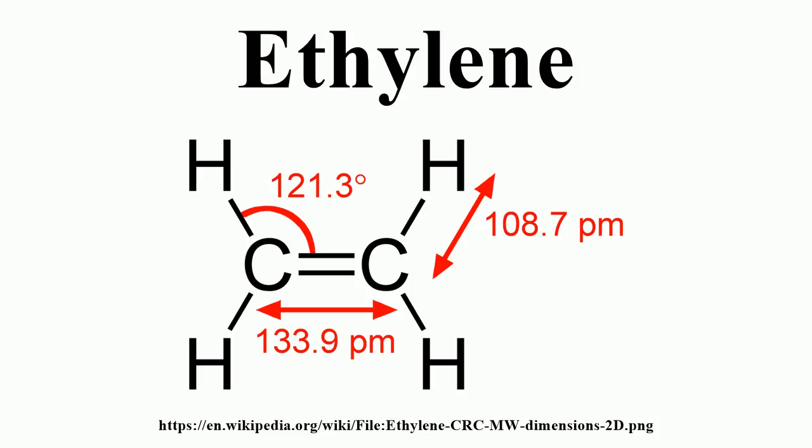The bottom stream from the deethanizer tower goes to the depropanizer tower. The overhead stream from the depropanizer tower consists of all the C3s that were in the cracked gas stream. Before feeding the C3s to the C3 splitter, the stream is hydrogenated to convert the methyl acetylene and propadiene to propylene. This stream is then sent to the C3 splitter. The overhead stream from the C3 splitter is product propylene and the bottom stream is propane, which is sent back to the furnaces for cracking or used as fuel.